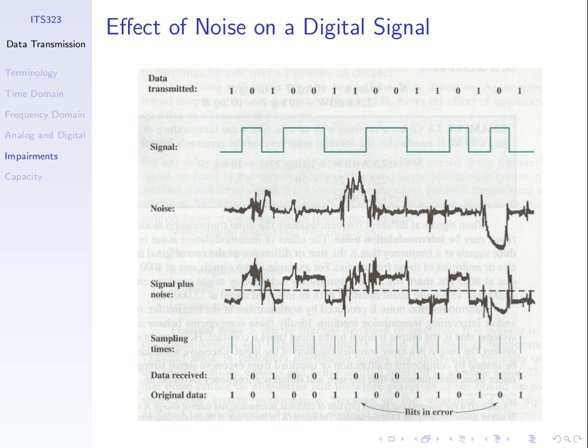What the receiver needs to do is get the bits back. We're sending bits from A to B. The bits are at the top. The receiver receives a signal, the signal plus noise here. They need to convert that back to binary. One approach is to measure the received signal every time period. If it's negative, it doesn't matter if it's -1, -1.1 or -0.9, but if it's below 0, assume bit 1. So at this sample point, measure the value.